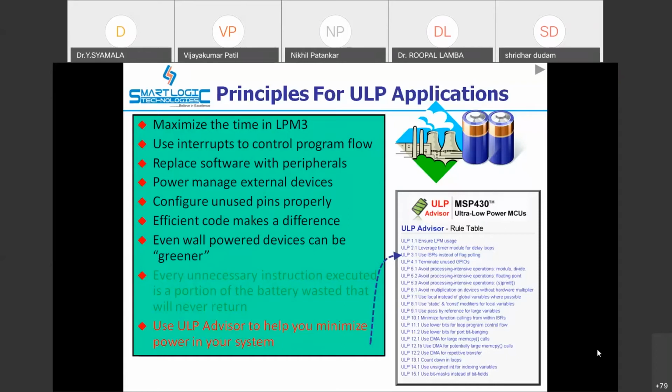Generally, the backlight is controlled through a transistor. If the transistor is on, the backlight is on. If the transistor is off, the backlight is off. That way, you have to control it. So that is a requirement. Even in the case of a TFT, take any one. Whenever you are talking about displays, the backlight takes a lot of the power. So if your system is going to be in a standby mode, try to cut down the supply of your TFTs.